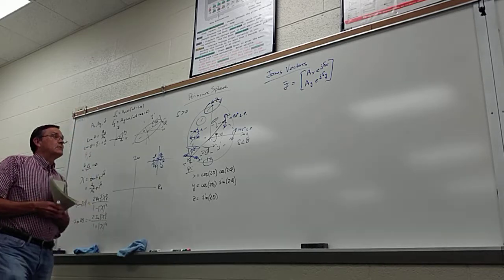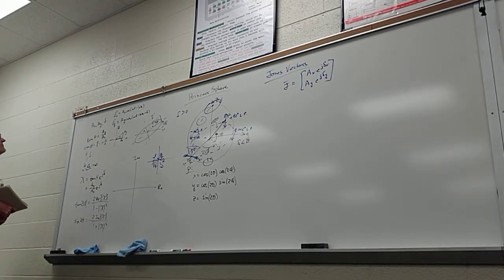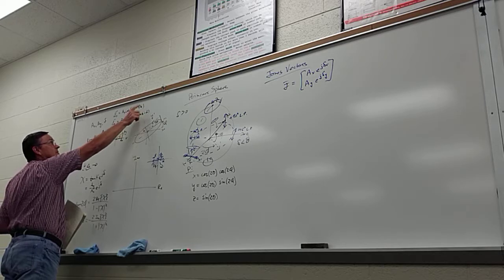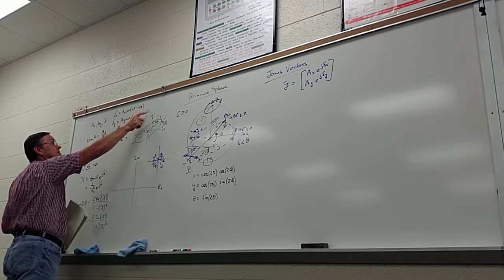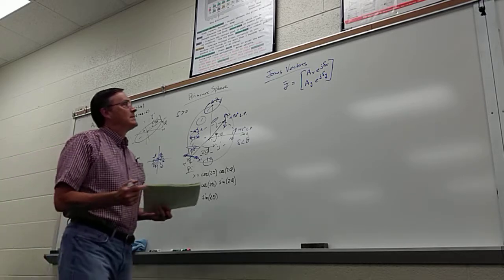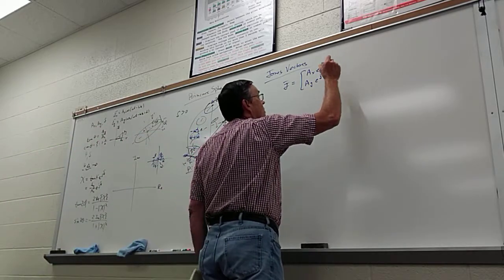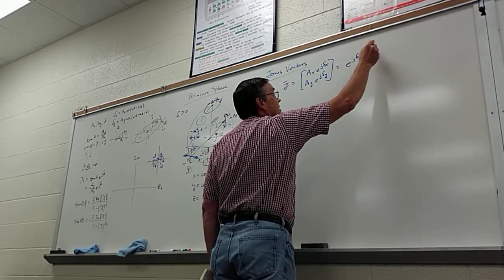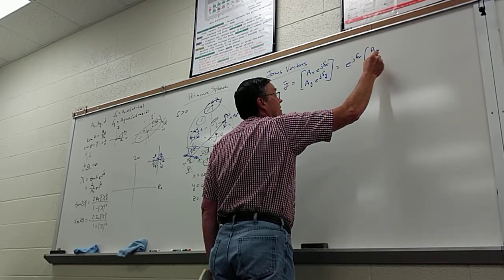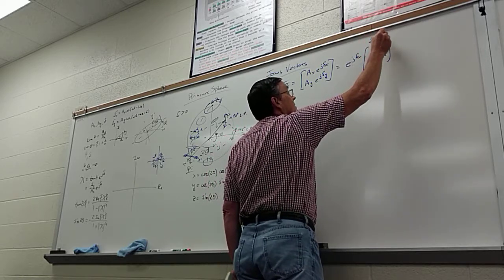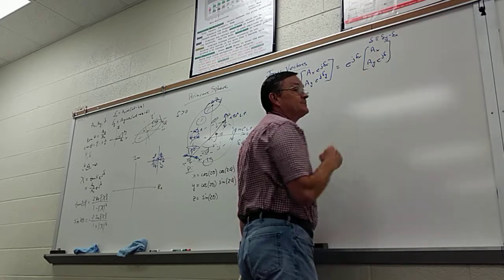And you look at that and you say, well, that looks pretty familiar. It's just this before I did the coordinate shift to get the x phase over here. And so we could take this and pull out e to the j delta x, in which case we have ax, ay e to the j delta, because remember, delta is delta y minus delta x.